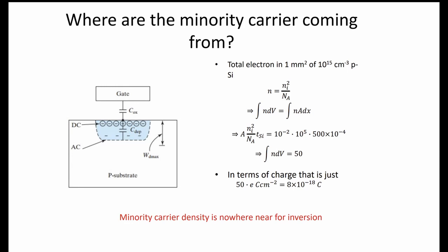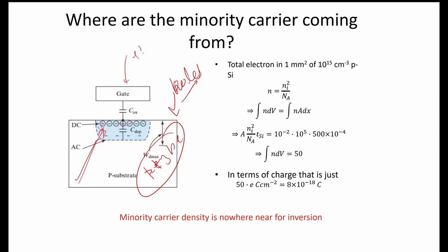As we have taken the p-type substrate, there are a majority of holes in this one, but we are creating an inversion layer of electrons by applying a positive voltage, so that we can create a channel at this junction for the conduction.